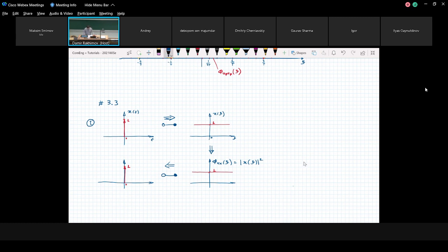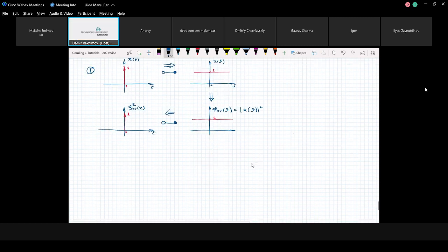But now it's our autocorrelation function, Rxx of tau. If you take a delta pulse and calculate the autocorrelation function, you get another delta pulse. If the original magnitude equals 1, the magnitude of the autocorrelation function will also be equal, but if you have different magnitudes, then you have to square it.